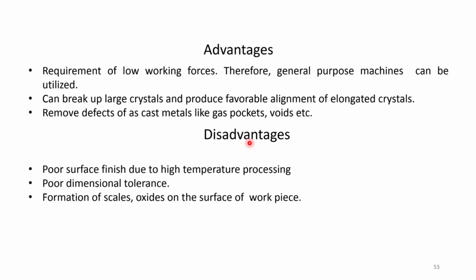The disadvantages: it has poor surface finish because of high temperature processing, and there will be poor dimensional tolerances, and there is formation of scales and oxides on the surface of the workpiece. At higher temperature, the material has a higher tendency to form oxides.